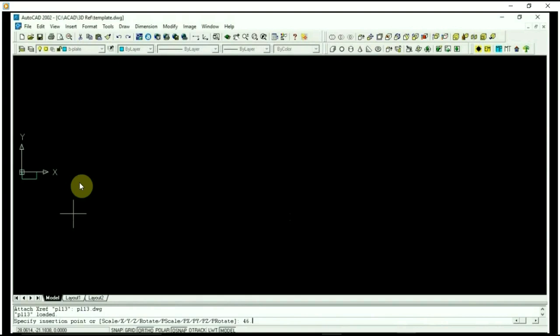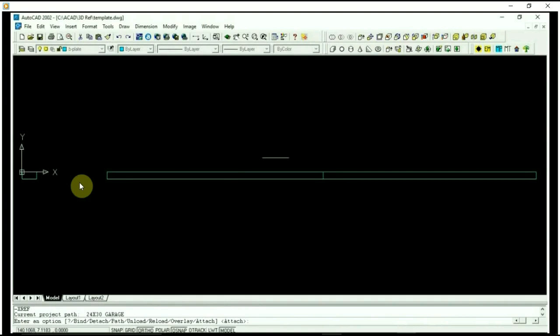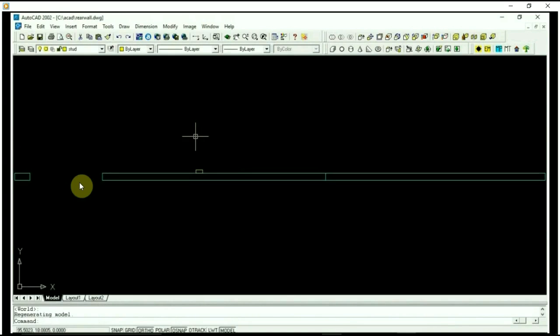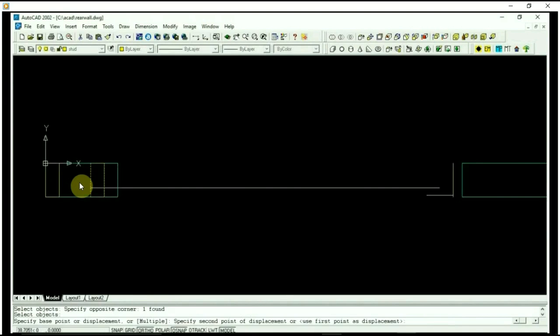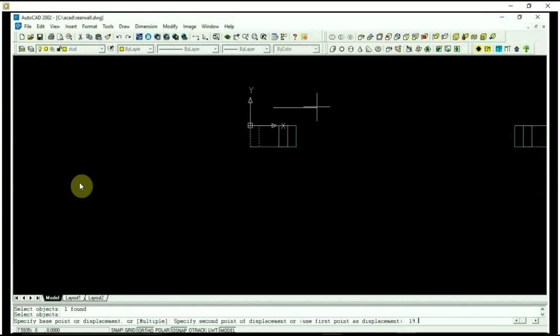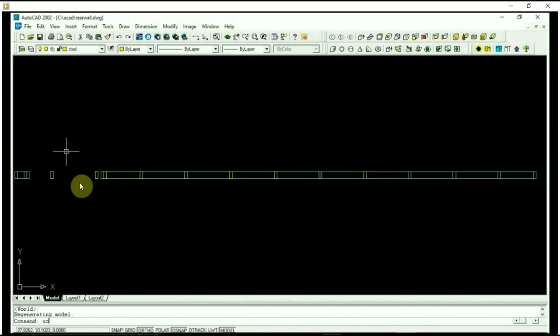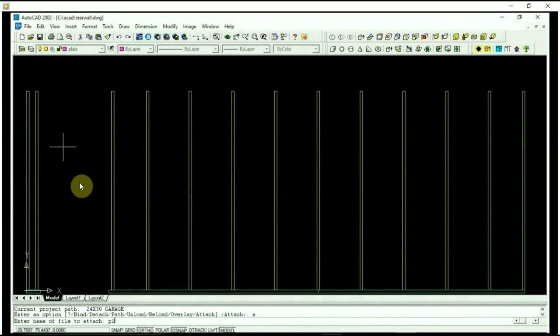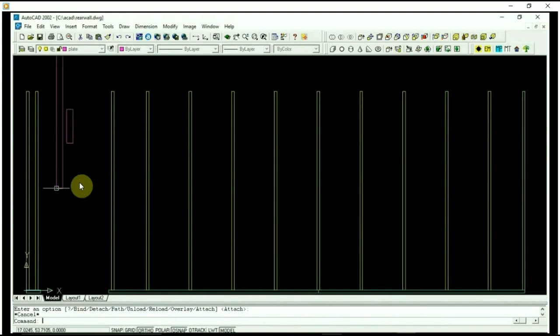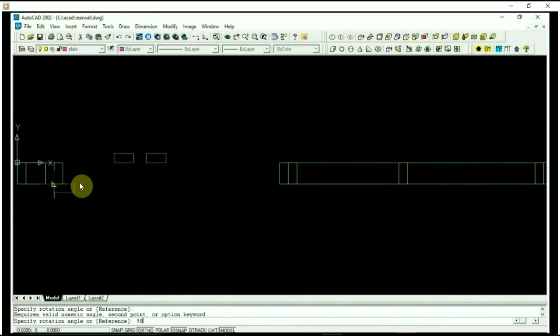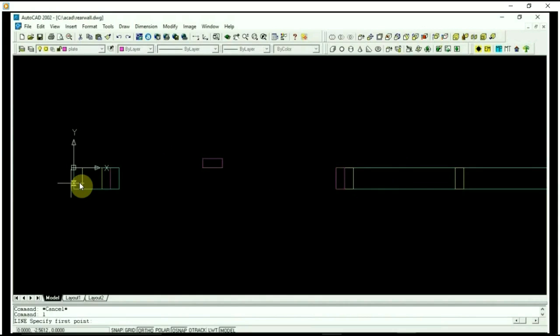If I try to do it in a 3D environment, what happens is I'll place them in two of the planes, and then when I go look at the third plane, it will have moved. And then I'll correct it in the third plane, and then I'll go back to one of the other planes, and by moving it in that third plane, it moved it out of alignment in one of the other two. And it's because of the snaps in AutoCAD. You might pick the top of a member, and it's actually picking the bottom, and so it'll move it vertically up and down in that third axis. So doing it in a two-axis system, just breaking components down so you can build them in two axes, is the way I would always suggest somebody do it, because it's a lot quicker and a lot simpler.